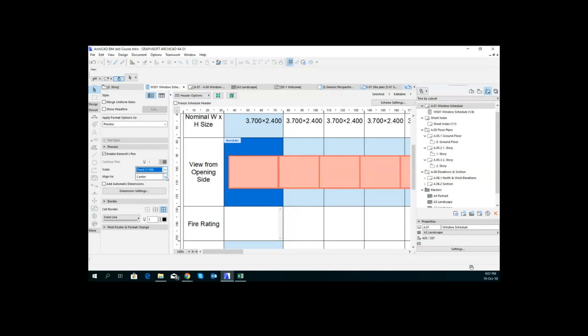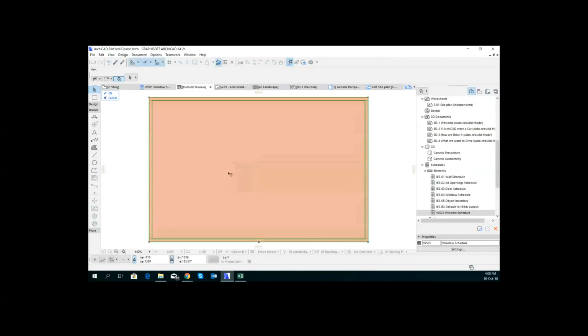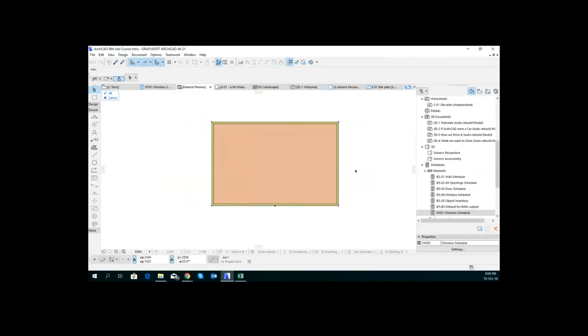So it can be fixed and you can set the alignment, and then you can get in there and start adding 2D information and data. So if you want dimensions, for example, you can generate that automatically. You just have to do those.